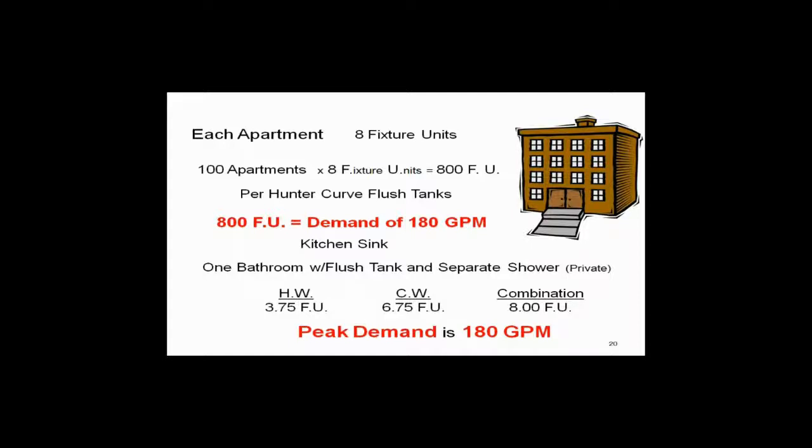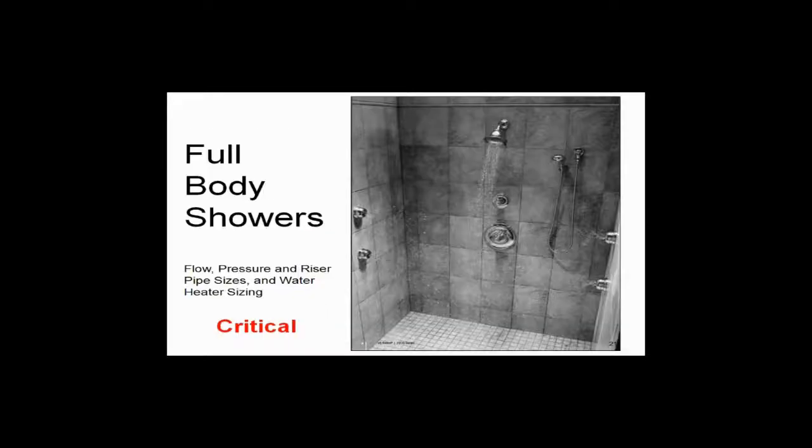And where did I get the 180 GPM from? We have to go to something called a Hunter's curve, which we'll do in a few minutes to make sure you understand where it came from. But before we assume that we got the exact right amount, I want you to recognize in the real world that we live in, people are putting in full body showers. And we can argue whether they meet code or not. And in fact, there are some lawsuits going on among some cities stating they don't. We don't want to get caught in all that. But the message is we just allowed 6 fixture units total for the bathroom, 2 for the water closet.